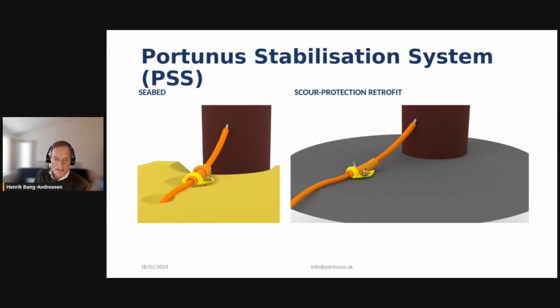The system is designed so that the PSS will actually be installed either right after the CPS is pulled into the foundation or anytime thereafter. So it can be retrofitted, it can be fitted right after the cable protection system is latched into the foundation during an installation, so for a new project, or any time after that. So retrofit can be obviously any number of years after it has been installed.